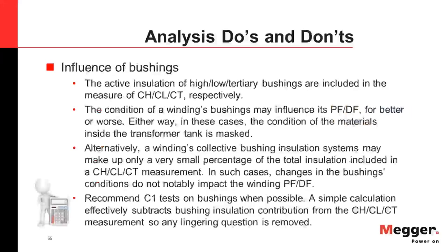The alternate is that the winding's collective bushing insulation system may make up only a very small percentage of the total insulation being measured in, say, a CH measurement. And so in these cases, any changes in the bushings' condition wouldn't notably impact the winding power factor, the CH power factor. So the only way to know whether bushings are impacting your results or not is to perform C1 tests on the bushings when possible,